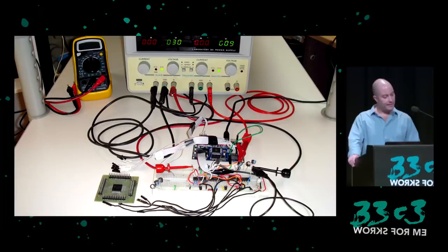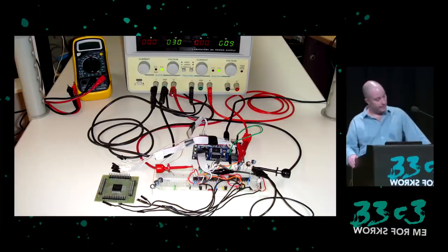To simplify the test setup as much as possible, the ACP was removed from the set-top box and soldered to a breakout board. So in this process, the battery-backed RAM was disconnected and all the keys were lost. But for the purpose of developing a working glitch, this was okay. This simple breadboard-based glitcher is quite flexible. The breadboard can be modified to test different ideas and reconfigured quickly. A more complex and advanced glitcher wasn't necessary.